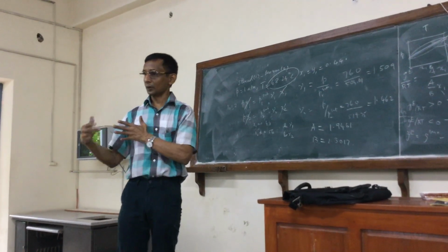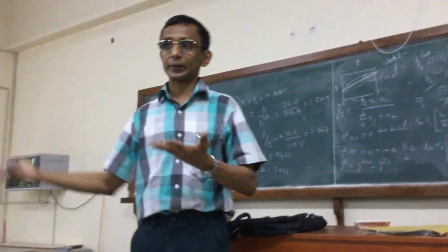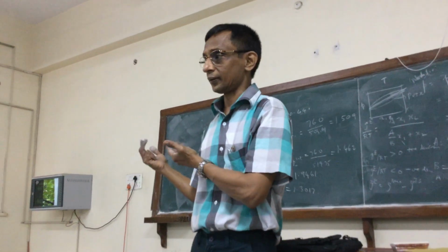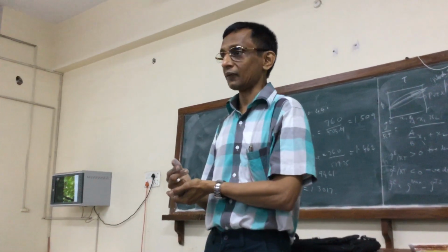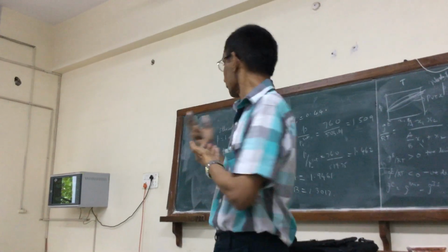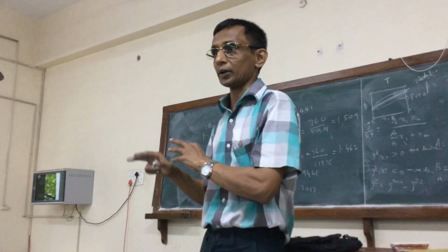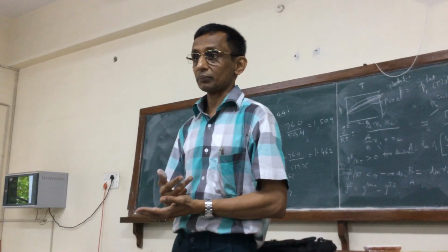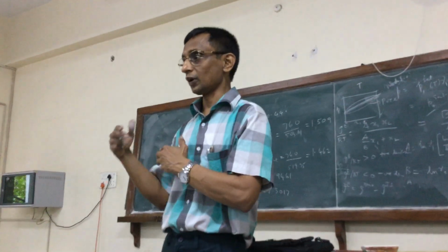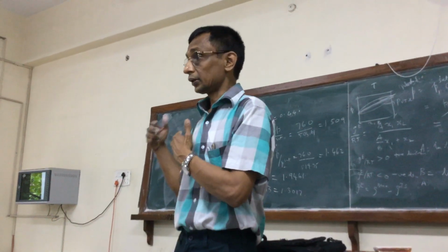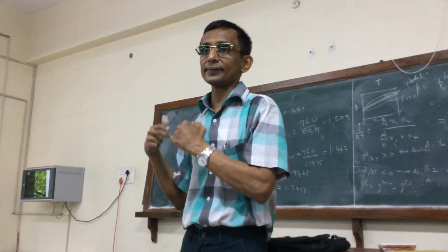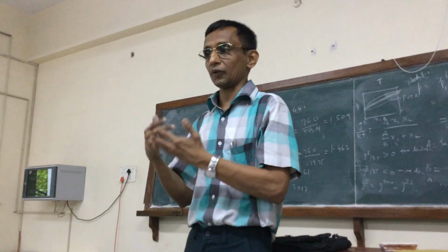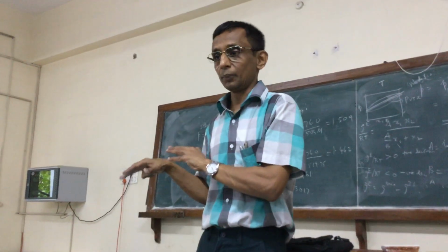Typically you are given a mixture, and parameters are available in table form. Sandler has a whole table of parameters for various mixtures. Other books also probably have it. By just looking at the Van Laar parameters, or probably similar things would apply to other models, you can say whether this is going to be a positive or negative deviation. But positive deviation does not necessarily mean that it has to exhibit a minimum boiling azeotrope. But if it exhibits an azeotrope, it has to be minimum boiling.